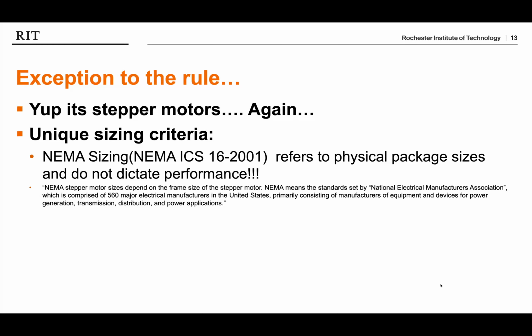In other words, a NEMA 17 motor of any length, shape, shaft size, dual shaft, notched, keyed, splined, any length will fit the same mounting pattern as any other NEMA 17 motor. And this can be very frustrating. So it always pays to pay attention, if you have to use stepper motors, to start with that mounting flange design and work your way back into other requirements.